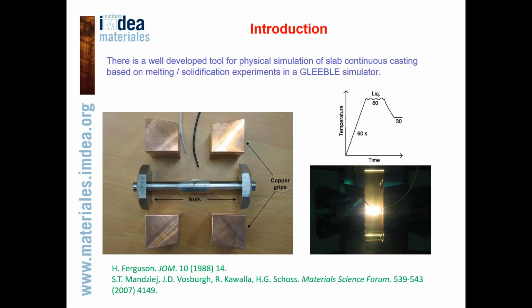The idea to use the ceramic shells came later. By that time, we had already accumulated a significant amount of knowledge on the melting solidification behavior of this material. And we knew that at temperatures above 1355 degrees, the midsection of the sample is fully molten.